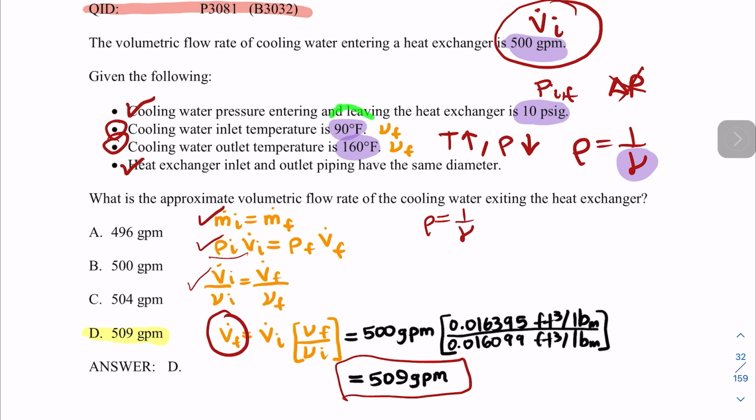but I think I jumped up some steps. So remember that this information we can get on our steam table, right? We can just go and get the specific volume at saturation temperature for my fluid, because I'm talking about water, so it's the fluid. Because I'm going to have in my steam table 3 different options, I'm just going to use the specific volume of the fluid.